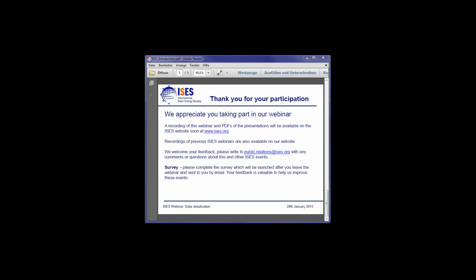So the first thing, from technical point of view, as I showed, MD is driven mainly by heat, by temperature difference, and reverse osmosis is driven by pressure, with a pressure pump. So it's basically completely different. With respect to maturity level, reverse osmosis was developed during the last 30, 40 years. So it's now applied in very large plants, up to 500,000 cubic meters. Membrane distillation is still only on very small scale.